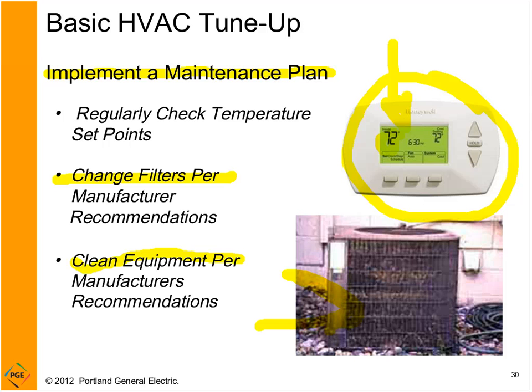You know, this picture here is of a condensing unit, and you have a unit like this on any split system, whether it be a heat pump or an air conditioning system. And this is where the heat gets rejected from your building. If you're in a cooling mode, the refrigerant gets evaporated inside, it gets condensed outside, and this is where the refrigerant is condensed and the heat is rejected. And so if you've got a dirty set of fins here, or if airflow is not flowing optimally through this, you're not going to have as much heat rejection, your compressor is going to work harder.